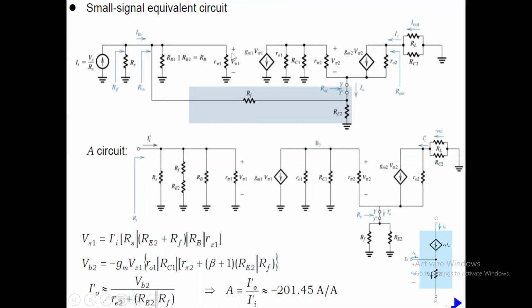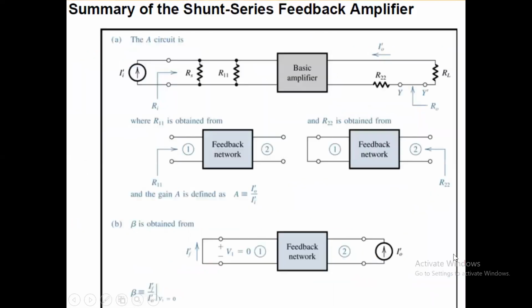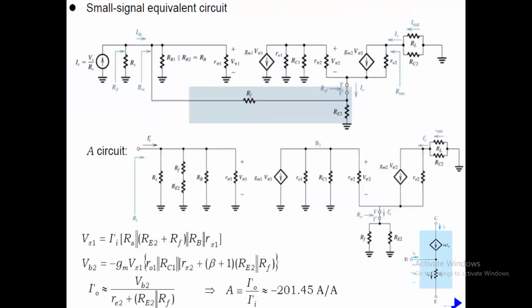Voltage across the R pi 1 is V pi 1, and then RC1 is there in parallel with it. This RC1, again, is going to go to ground, and RC1 will come. And this can again be replaced by the same type of model, or better, you can replace it by this. But in this figure, only the pi model is written.